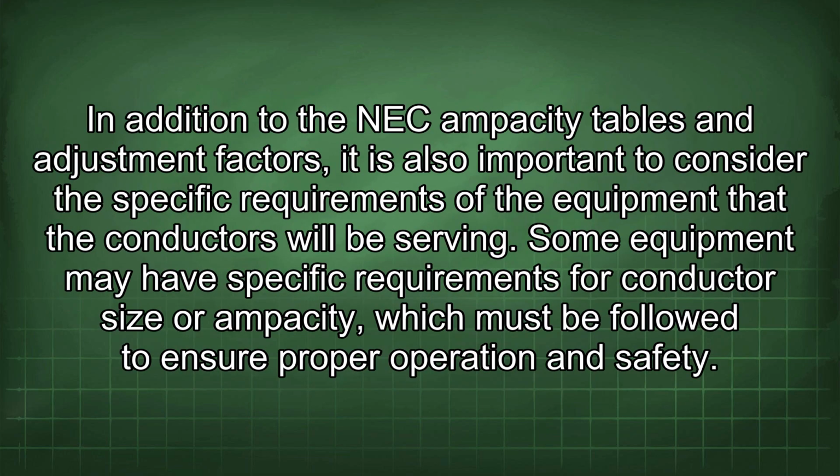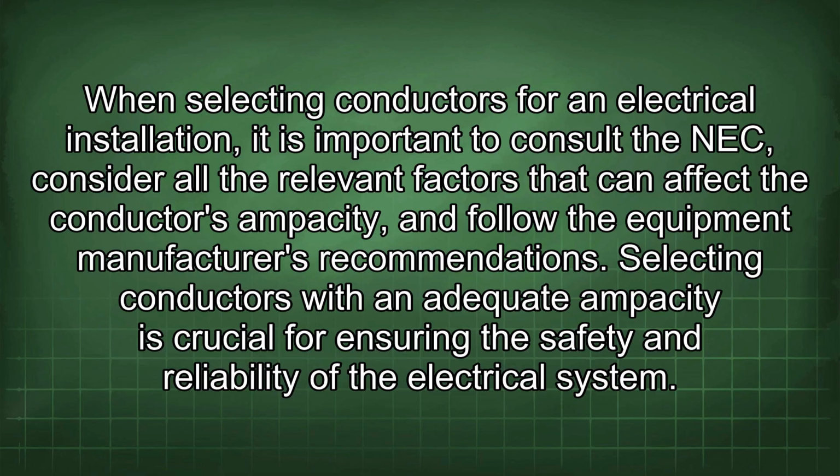In addition to the NEC ampacity tables and adjustment factors, it is also important to consider the specific requirements of the equipment that the conductors will be serving. Some equipment may have specific requirements for conductor size or ampacity, which must be followed to ensure proper operation and safety. When selecting conductors for an electrical installation, it is important to consult the NEC, consider all the relevant factors that can affect the conductor's ampacity, and follow the equipment manufacturer's recommendations.